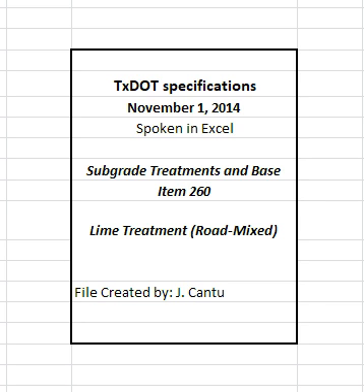2.6 Mix design. The engineer will determine the target lime content and optimum moisture content in accordance with TEX 121E or prior experience with the project materials. The contractor may propose a mix design developed in accordance with TEX 121E. The engineer will use TEX 121E to verify the contractor's proposed mix design before acceptance.